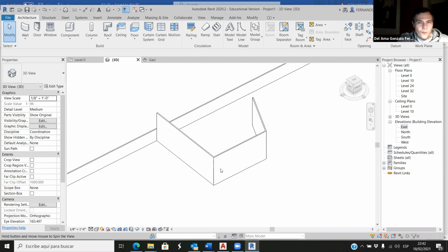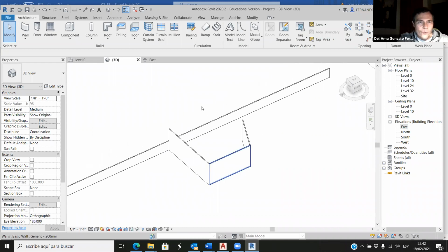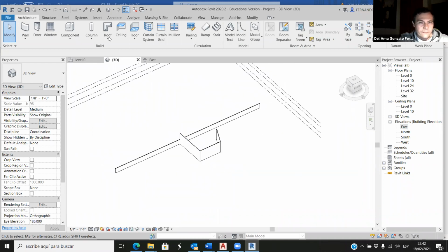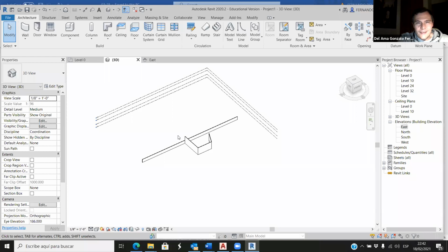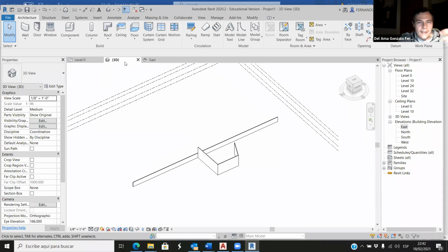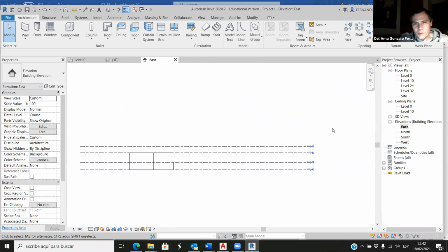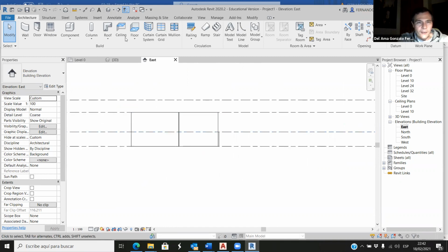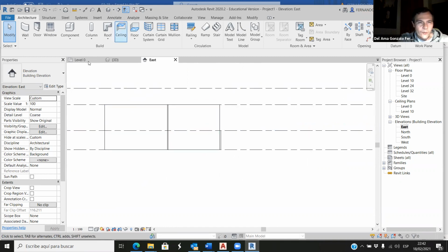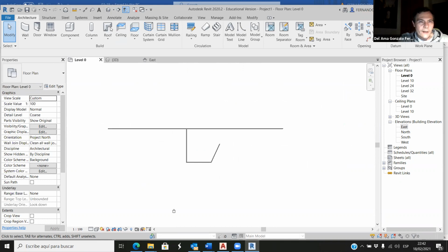We have walls. What else do we need? We would need a roof. So let's try to work with roof. But when we are working with roofs, we need to understand what level we are in. A roof doesn't mean that we are in the last level. Okay, so you remember that we have level 0, level 10, and level 24. So those walls are up to level 24. So when we are in level 0 now, if we are placing a roof,